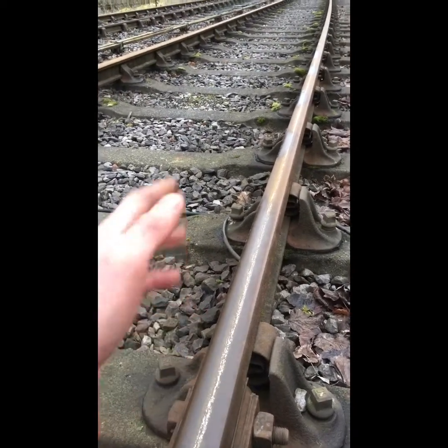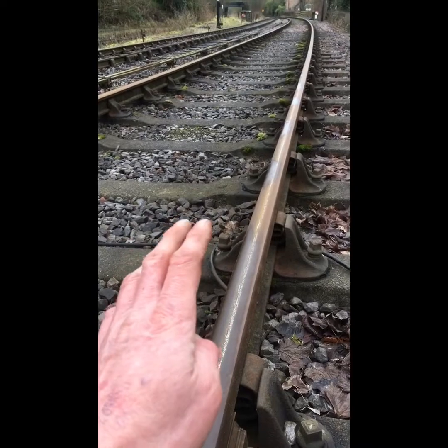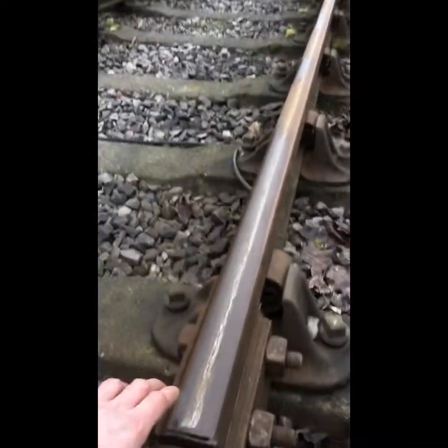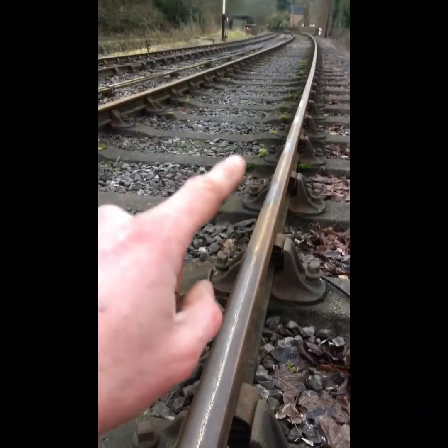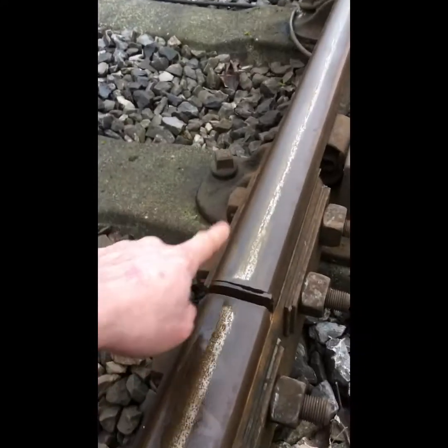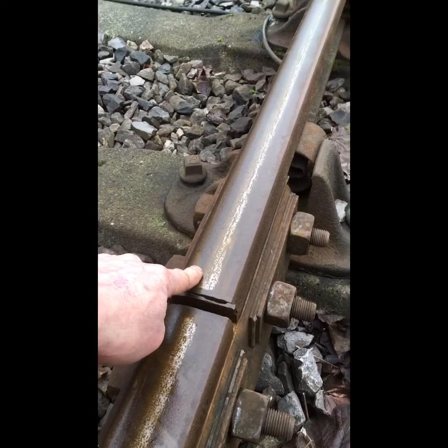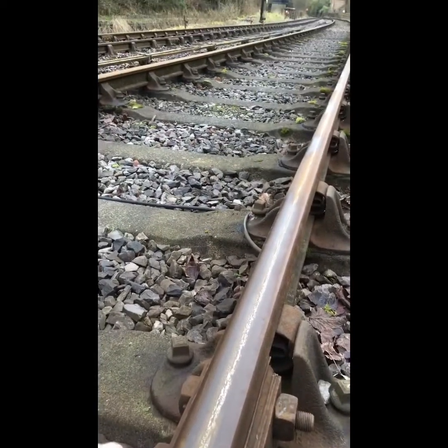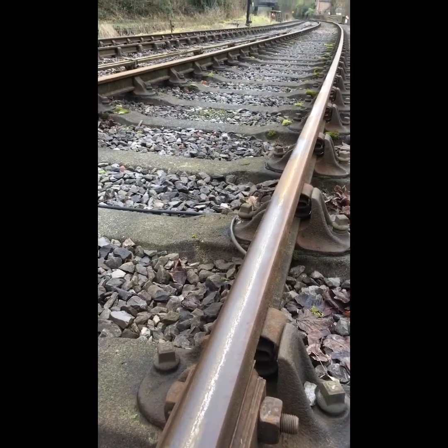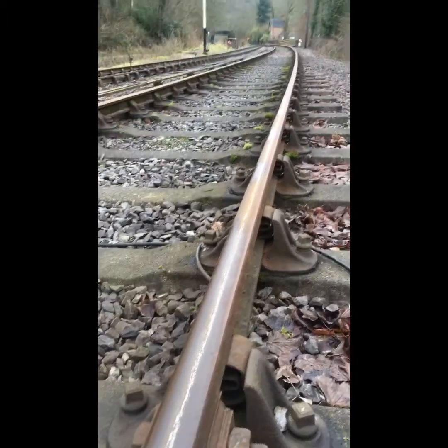And also moving off to a different subject would be AC track circuits. AC has a tendency to go a lot further than a DC track circuit, and also tends to blast through the railhead contamination quite a lot. We don't suffer much with the leaf fall problem that a lot of railways suffer, because obviously we run heritage trains which are heavier.